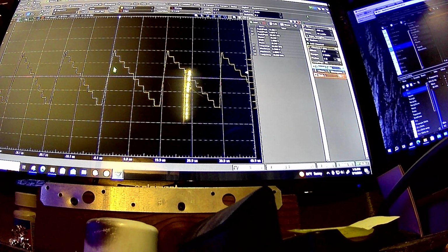They all would have the same slope if you were to actually measure it, and that's going from here to here, for example, versus here to here. What they'll do is put a low pass filter set so that anything above 500 kilohertz or so, in this case, would go through a low pass filter and be filtered out. And it smooths it out a lot, because a lot of these are really representing higher frequency components, all right?